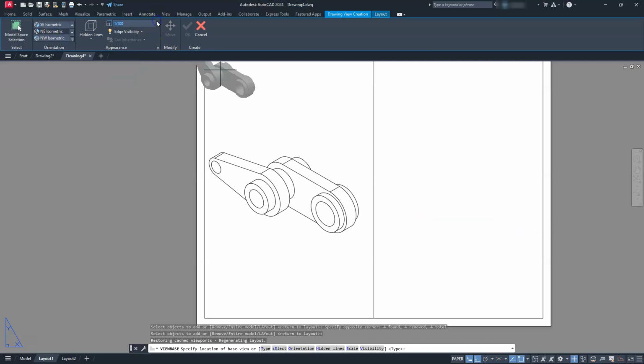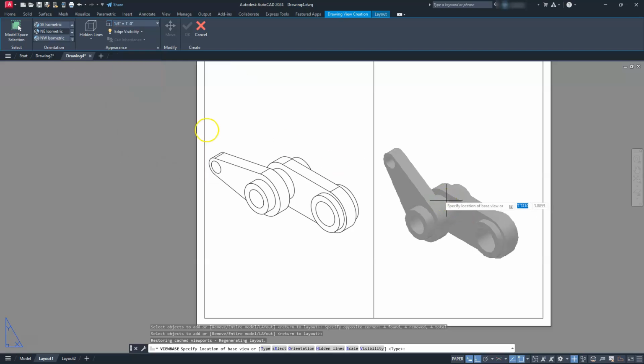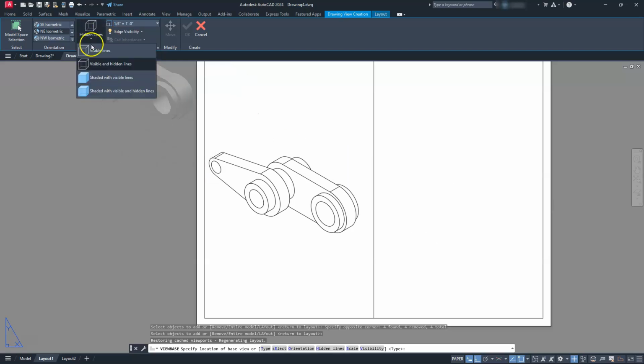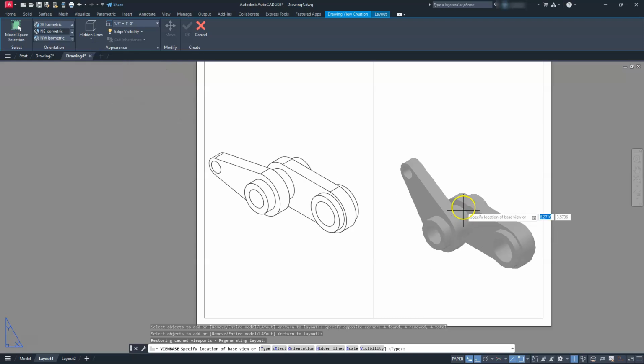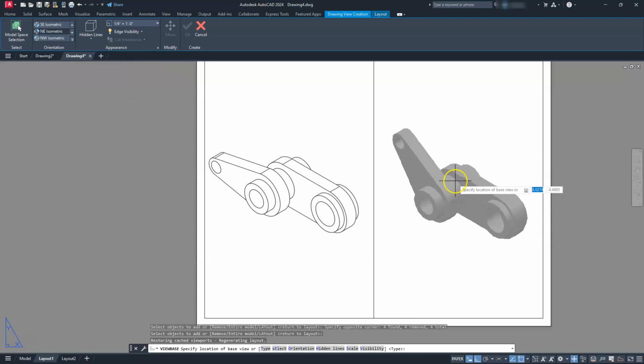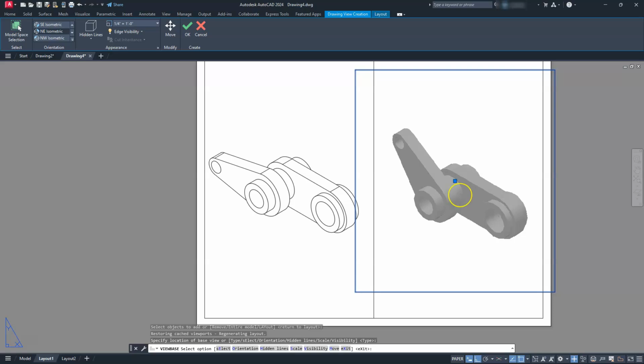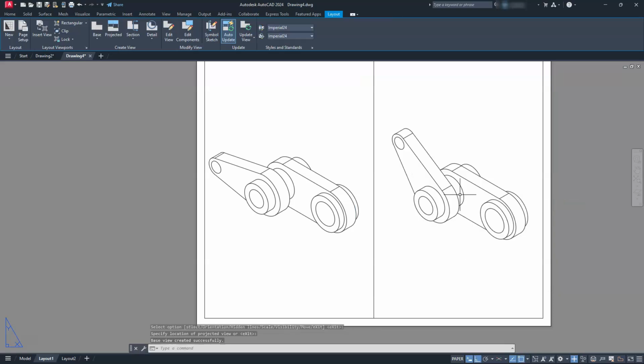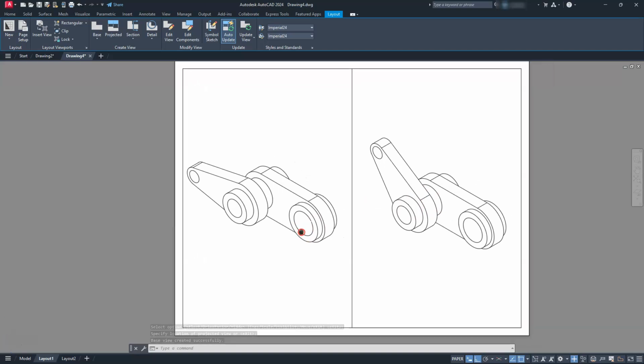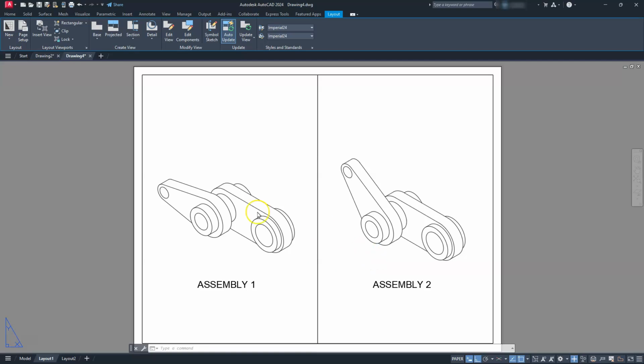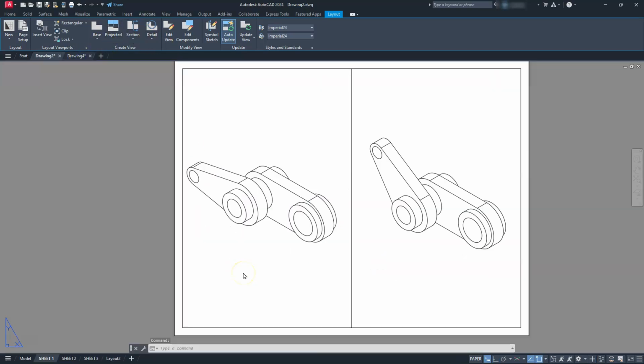And then I'll go ahead and adjust the size of this one as well to, I think I used 1/4 inch. And let's go ahead and change it from hidden lines to visible lines. And then I can go ahead and click here. Hit enter, and then another enter, and then you should have your view created, right? So now if you take a look, that view looks really similar to these two views, right? So we did that rather quickly, and we can put the text on here.